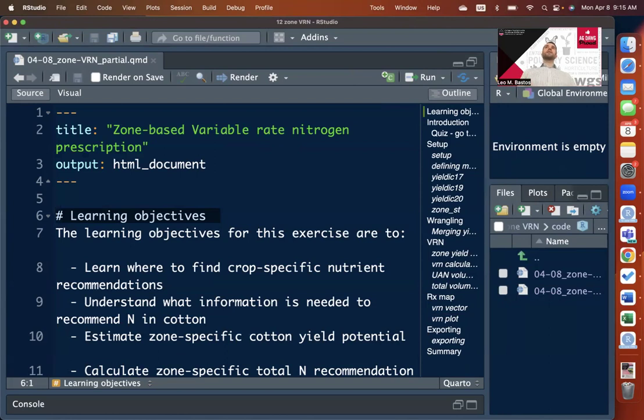We also brought in electrical conductivity data, interpolated it, exported it as 2 depths, and then merged all of that into the same file and created the zones. We smoothed the zones, which as you saw in the last exercise was an important step, and exported the zones.